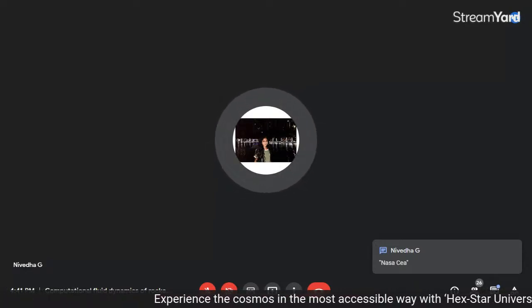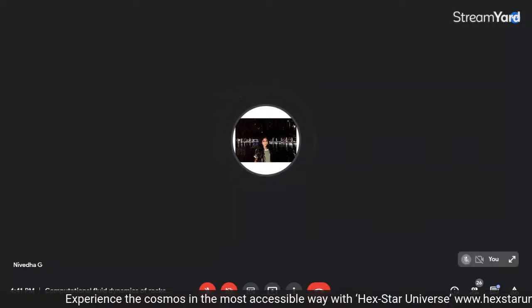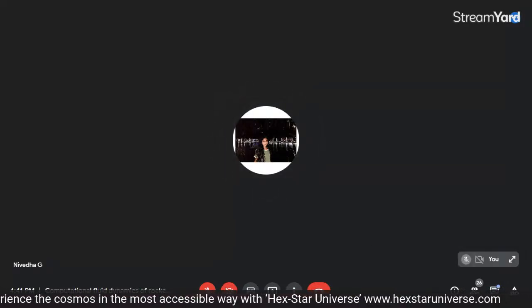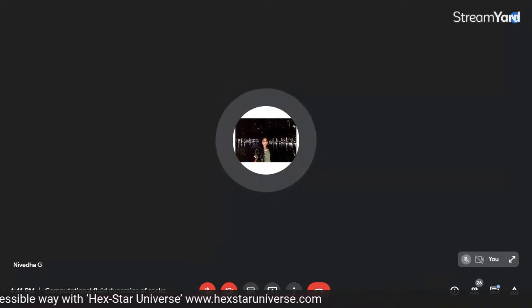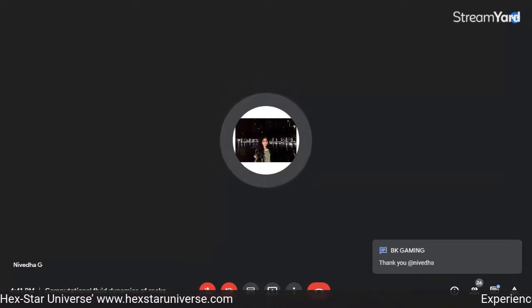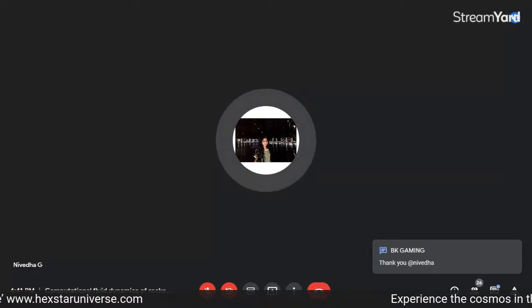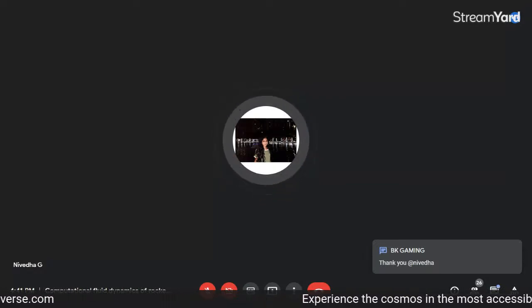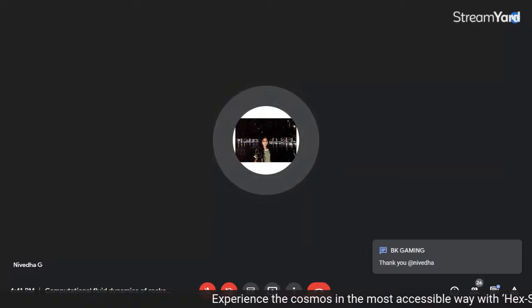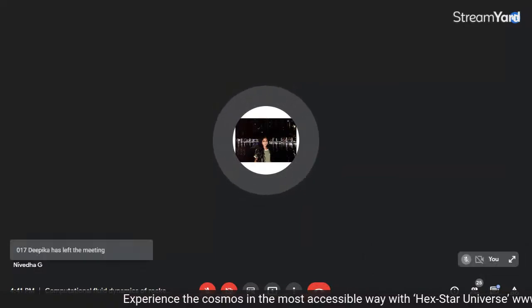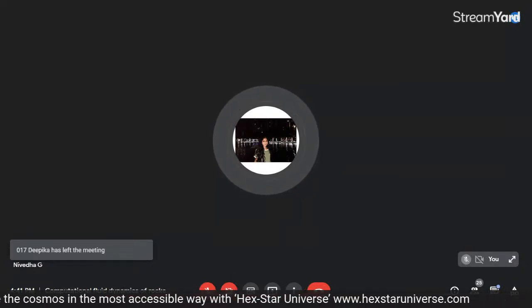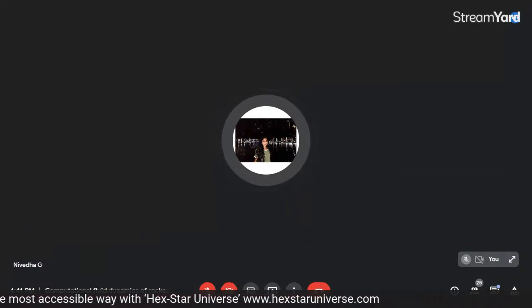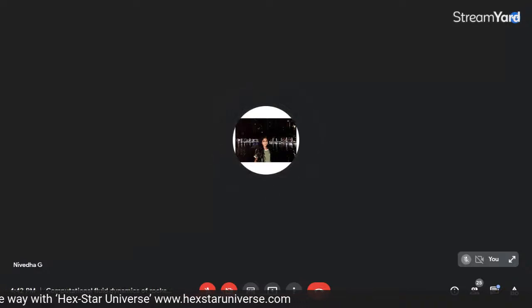Which type of mesh do you prefer for the normal mesh? There is no preference in this. What I did was just a trial and error method. Since it was just a 2D drawing, I just did it by the number of element method with bias and reverse bias, and that's it. I just made a mesh which has to be fine. That's all.